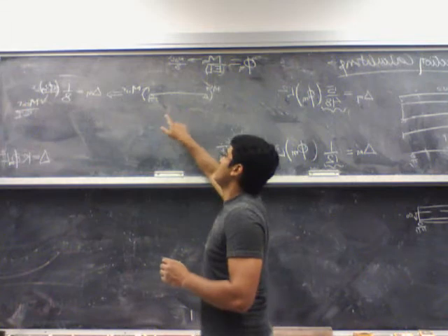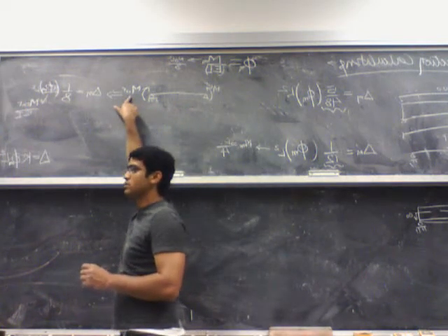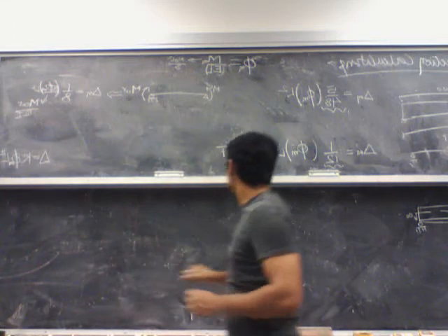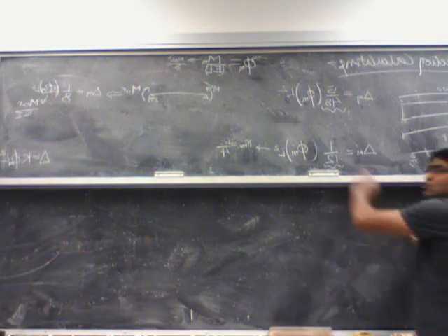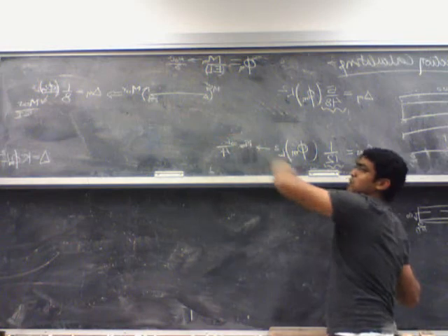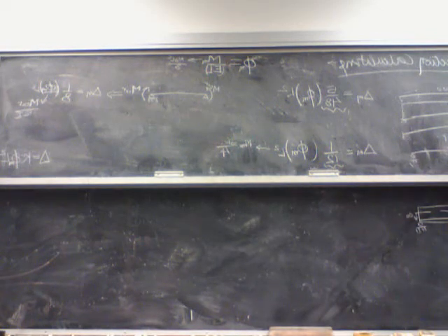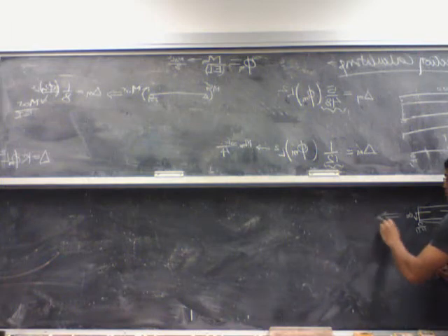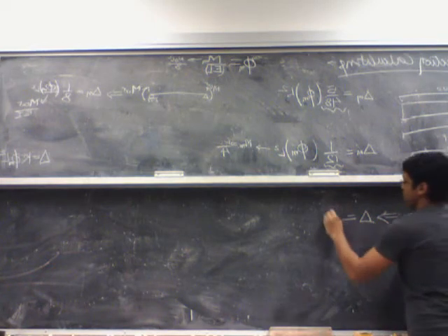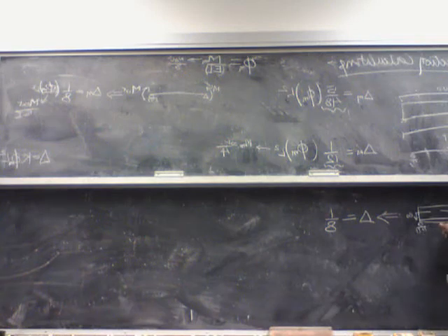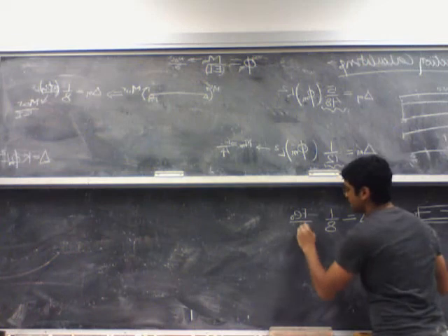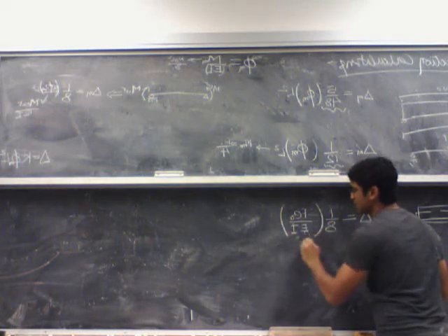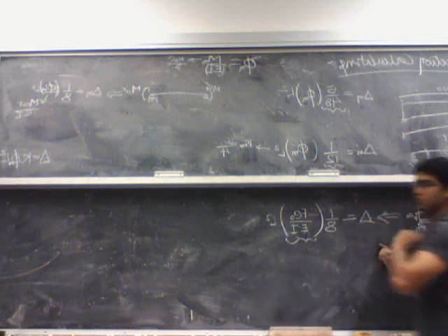The only difference is that in the last case I was applying an external moment. Here that external moment is caused by the pre-stressing force and the eccentricity E naught. But technically these two are exactly the same cases, because they both create constant moment throughout the span. So for this case, my delta is simply 1 over 8 times the moment, which is minus F times E naught divided by EI. This gives me the curvature at the midspan, times L square.